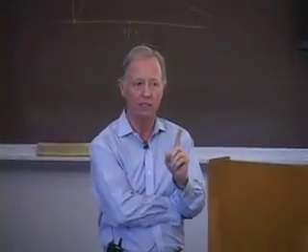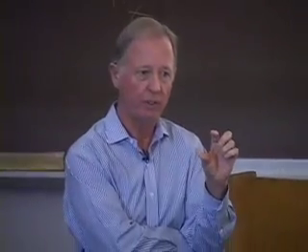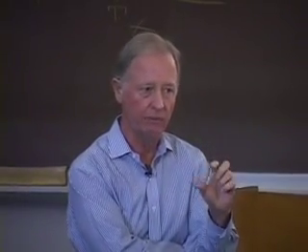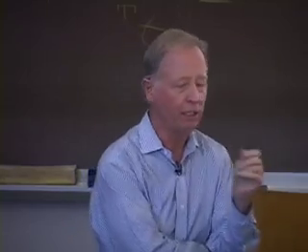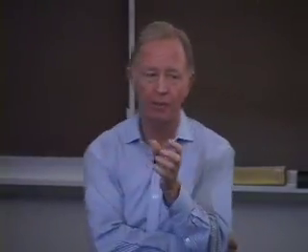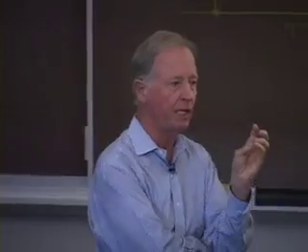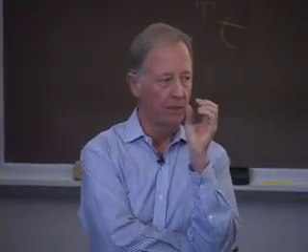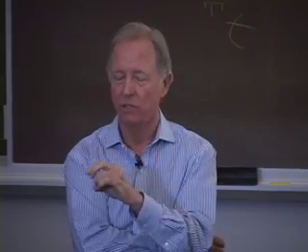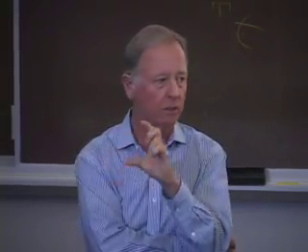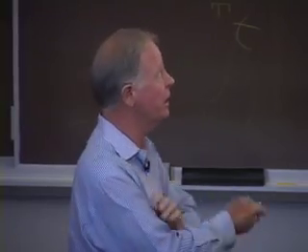That's the key thing you want to ask. I've got my dependent variable, which is C1, and I've got my independent variable, which is time. How can I combine any of my given parameters in such a way as to create parameters that have the same units as either concentration or time that I can use to normalize, that is, non-dimensionalize